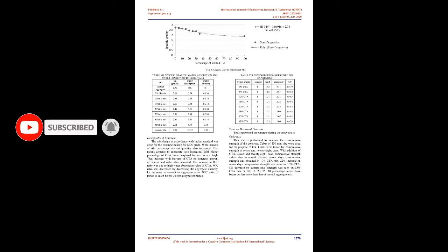Water absorption and specific gravity of aggregates are needed to be determined. The mix designs are based on specific gravity and water absorption. The tests were performed in accordance to IS 2386 Part 3. Flakiness and elongation index. Flaky or elongated materials, when used in the construction of a pavement, may cause the pavement to fail due to the preferred orientation that the aggregates take under repeated loading and vibration. It is important that the flakiness and elongation of the aggregate are contained to within permissible levels.